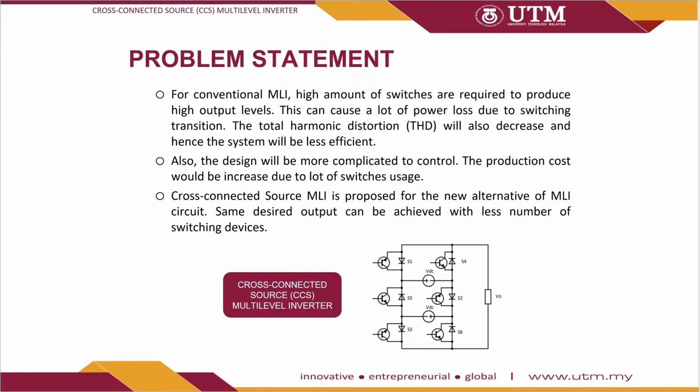In this video, we will see how both the conventional topology, specifically the cascaded bridge, and the new topology, cross-connected source, actually work. We will also analyze all the performance, including various modulation indices. All the analysis focuses on simulation only, using Simulink MATLAB.